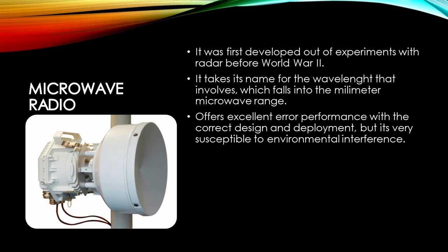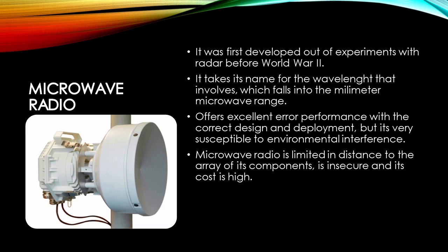This technology offers substantial bandwidth and also excellent error performance assuming proper systems design and deployment. Physical obstructions must be avoided at all costs because of the phenomenon of Fresnel zones. Microwave radio also is particularly susceptible to environmental interference such as haze, smoke, fog, and precipitation. Microwave clearly is a distance-limited technology, especially at the higher frequencies.